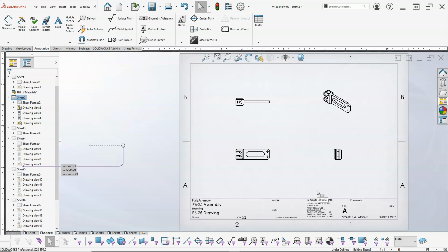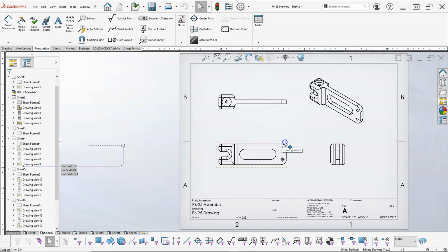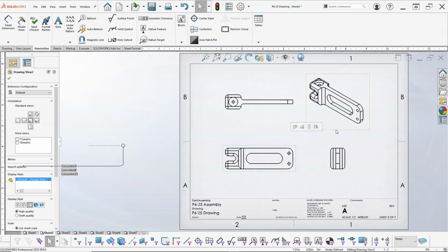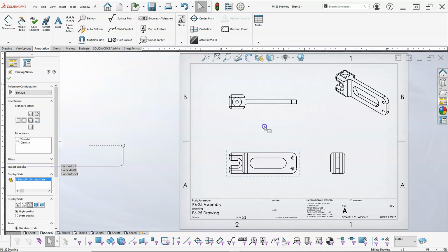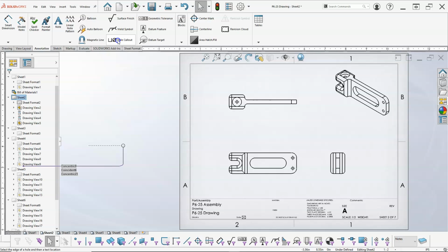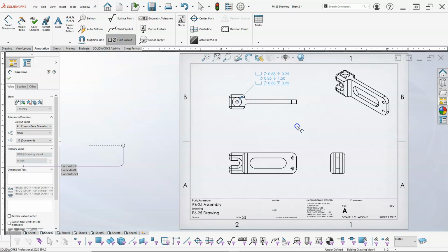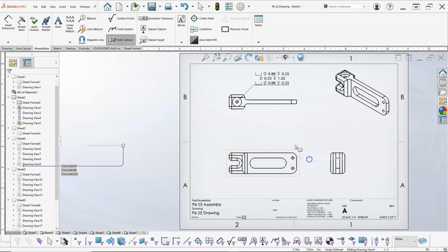All right, so back to this, size-wise. Let's see what the 1/2 looks like. Those radiuses still drive me crazy. I think it's a lot more detail than it needs. Let's see what the hole callout will do with that specialized hole stack-up that we did. All right, so near side, far side. So that would be the only thing if these were different.